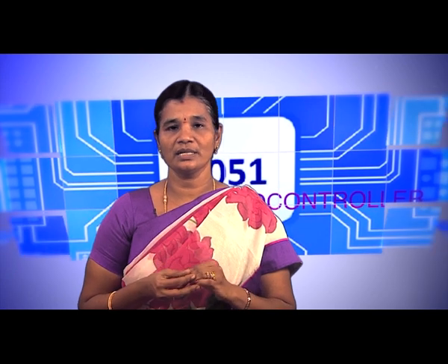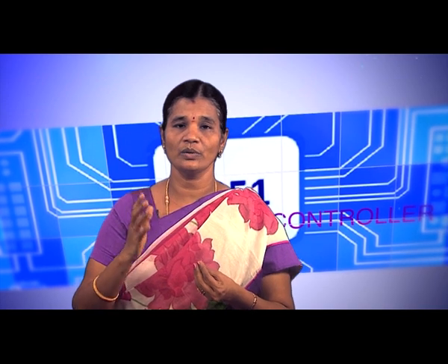In arithmetic instructions we can use addition, subtraction, multiplication and division, along with increment and decrement. For these, one of the data should be loaded in the accumulator and the other in a register; for multiplication and division it should be in B. The resultant is stored in the accumulator. That is one of the advantages, which is why the accumulator is called a special register.